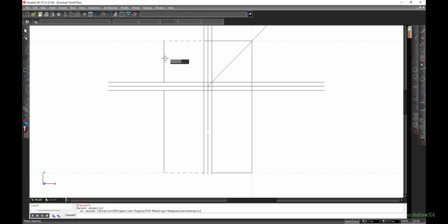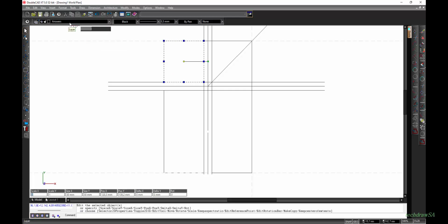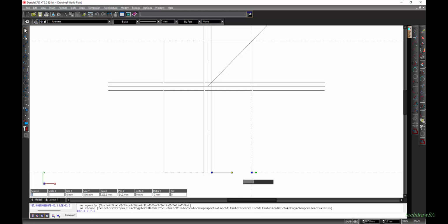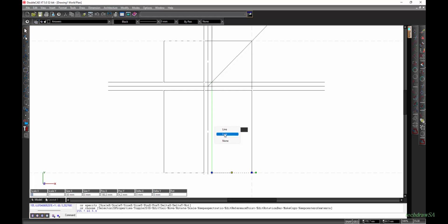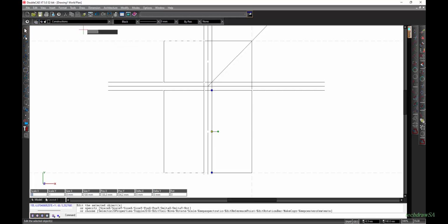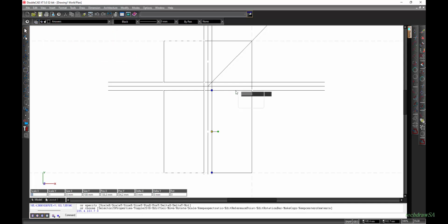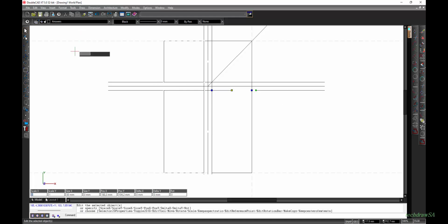Good. Now if I want to select that top view, you will see it's the answers layer. If I select that front view, you'll see it's on the answers layer. But now if I select that line, it only selects the one that I clicked on, because we drew these as single lines. But it does show it's on the right layer. So I can click on that line and see it's still on the right layer. And if I click now on this one, I have to select the one that is applicable, in this bottom one, and that will show that it is not on the correct layer. So now I click on the drop down and drop it on the correct layer. And now I do the same with this one. I select the second option, and that one is on the correct layer.